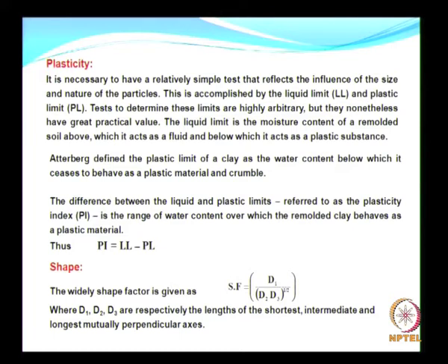The complete description of the liquid limit and plastic limit you can get in any standard civil engineering book, I mean soil mechanics book. Atterberg defined the plastic limit of a clay as the water content at which it ceases to behave as a plastic material and crumbles.